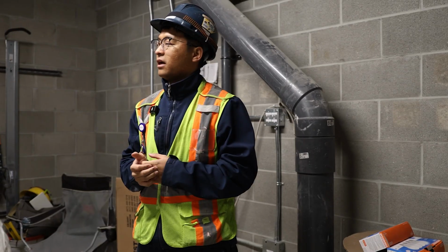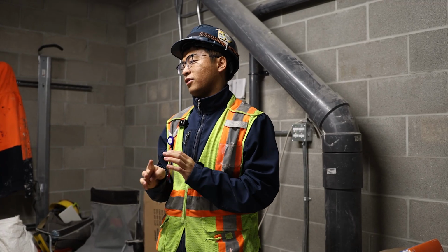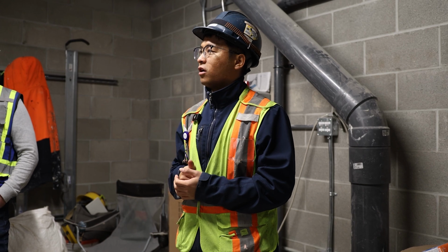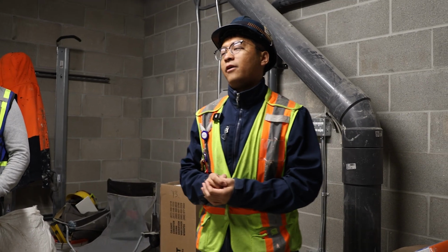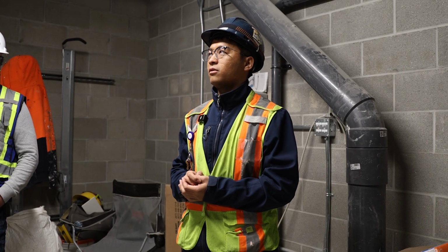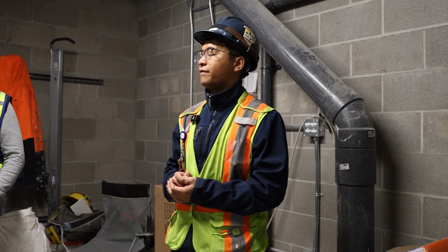It's under BMS, yes. Yes, you are able to change the space temperature set point. You are also able to override the supply temperature set point. It's in inch water column, yeah. Normally, I would do 120 Pascal. 120, okay. Pascal, that's 0.5 inch water column. Okay, so 0.5, yeah.